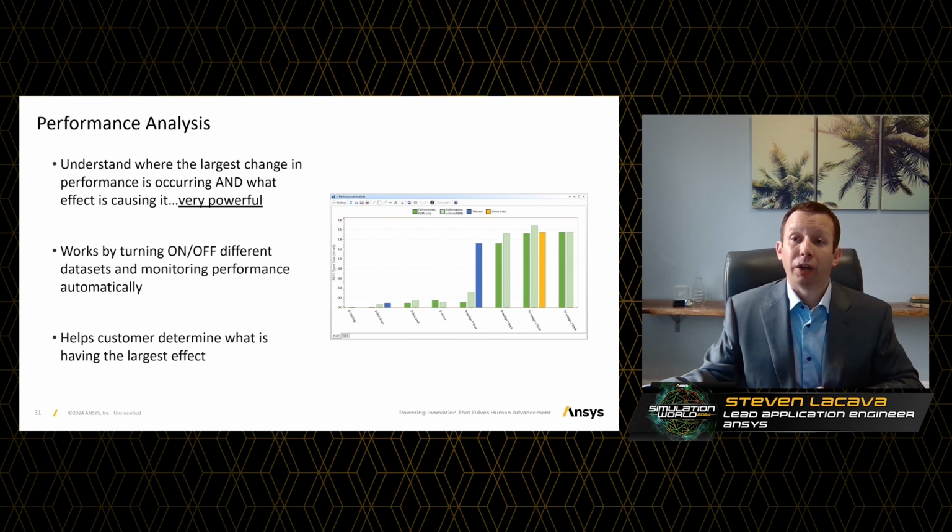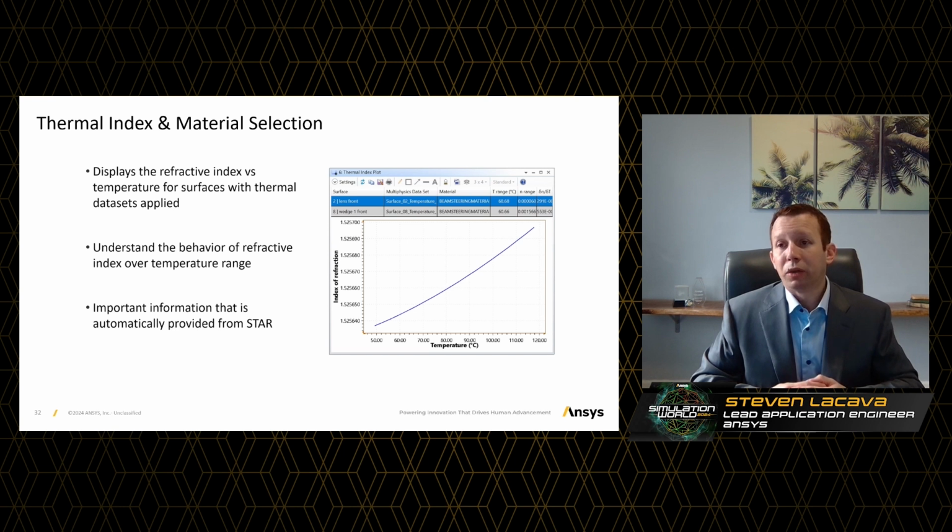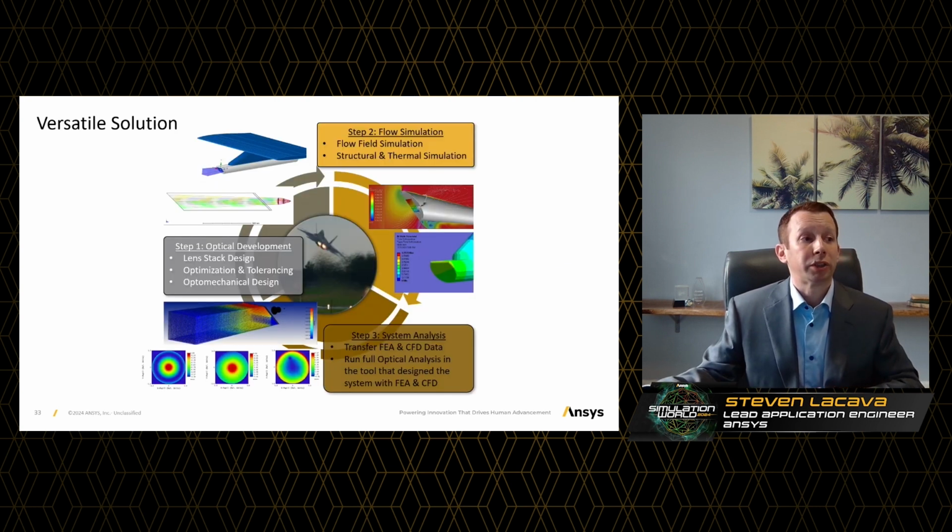And all of these can be turned on and off element by element within your system to really allow you to interrogate the light. Finally, once we make those changes, just like we did in the stop analysis, we can go ahead and look at different material classes. And we can look at how those materials are affected by temperature and thereby select better materials for future analysis.